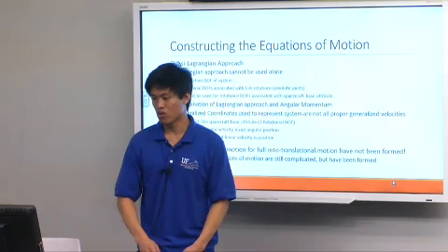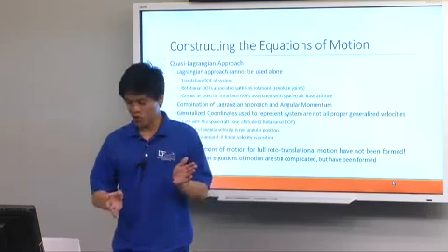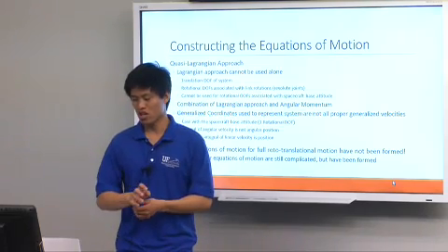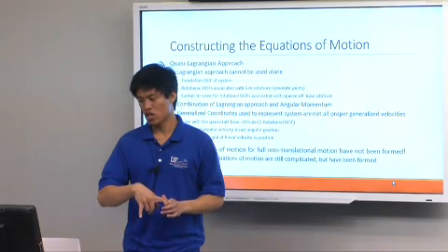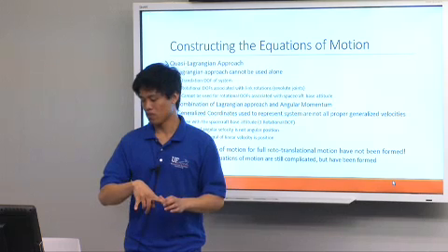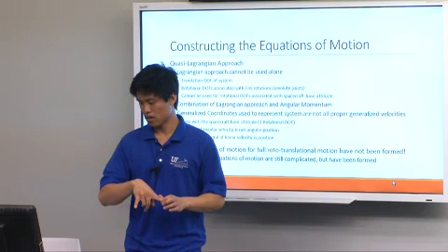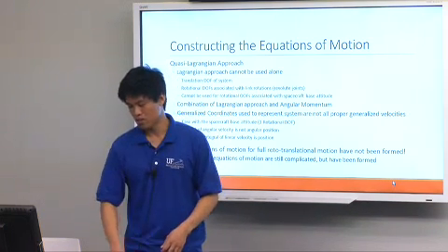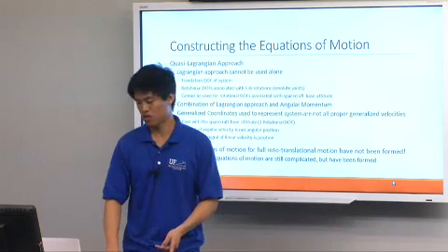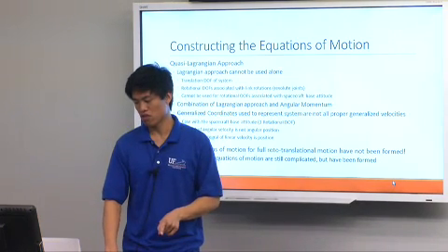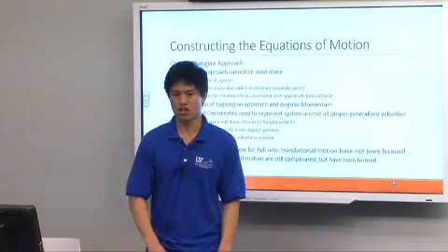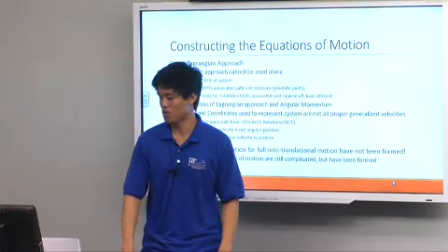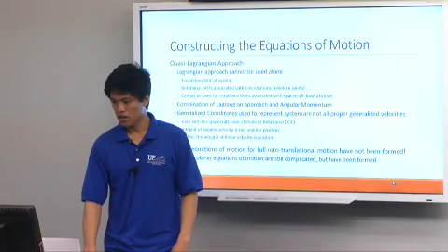So for the equations of motion corresponding to the spacecraft base attitude, we use angular momentum. Again, the point is that the integral of angular velocity is not angular position, unlike the integral of linear velocity, which is position. That is a key point in this approach, and that's why it's called quasi-Lagrangian, because it's a combination of both methods.